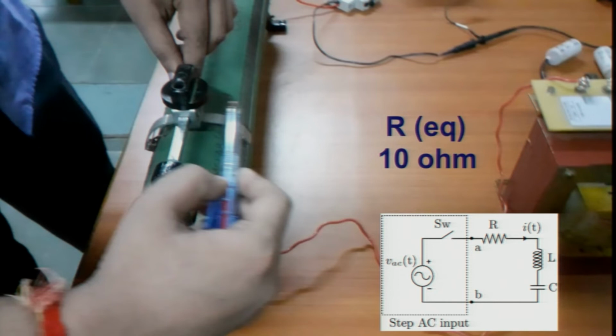If you are doing this experiment right after you did the previous experiment, the capacitor would still have some charge. Eventually, it would discharge through parasitic resistances across its terminals, but what you need to do is to discharge this capacitor if you want to start from 0 initial conditions.